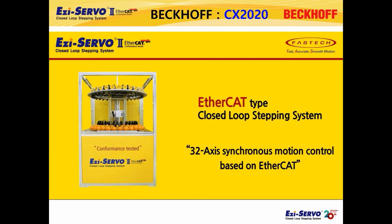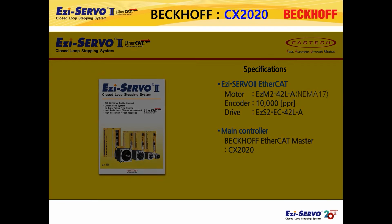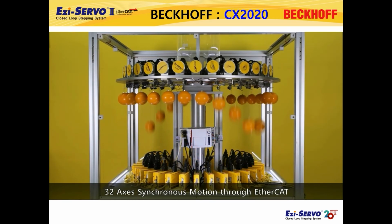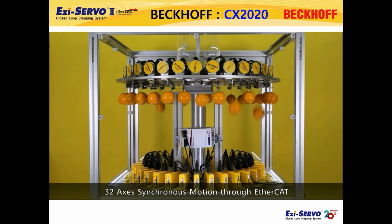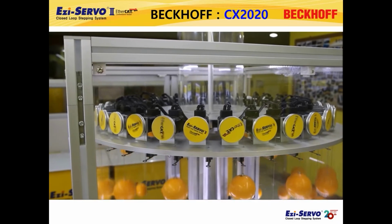The next demonstration shows synchronous control of 32 axes of Ezi-SERVO II EtherCAT using German Beckhoff's EtherCAT Master. The product names used in this demonstration are as follows. EtherCAT has a high communication speed based on 100 Mbps high-speed Ethernet, so even if the number of axes increases, synchronous control can be performed at a high speed. In other words, EtherCAT is optimal for multi-axis control.